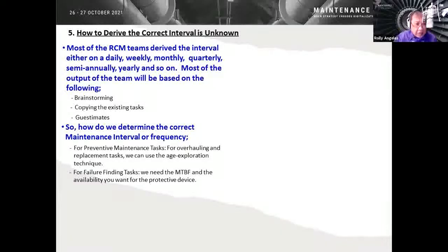Okay. Now, for routine inspection, we can use MTBF because MTBF is an average, okay, but you just lessen the value by 10%. So if the MTBF is 1 month or 30 days, we need to perform the inspection before reaching the 30th day. Okay.